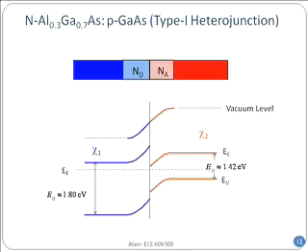There are possibilities here that homojunction transistors, silicon transistors, of course wouldn't have. Right. So, okay, you know how to draw a band diagram then, and these would be called abrupt heterojunction transistors, because one material abruptly stops, the emitter stops, and then another material begins. The composition of the material doesn't change as a function of position. What is the composition? You can see on the top that 30% of the gallium atoms in gallium arsenide have been replaced by aluminum. So that's what it says, aluminum 0.3, gallium 0.7, and arsenic, that's for the emitter region, and that's 1.8.